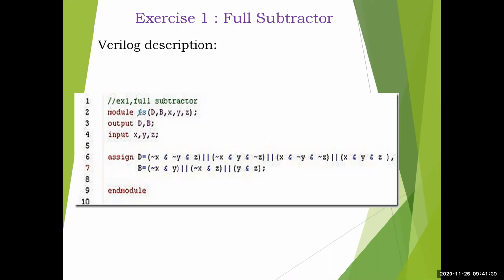The module name I have given is fs, for full subtractor. Then the inputs and outputs are written as a list of ports: x, y, z, d, b. The outputs are d and b, so that's why output is declared, and the inputs are x, y, z. The expressions are already done, so just assign statements are used. You can use two assigns with a semicolon at the end, but since a comma is used, one assign holds both statements.